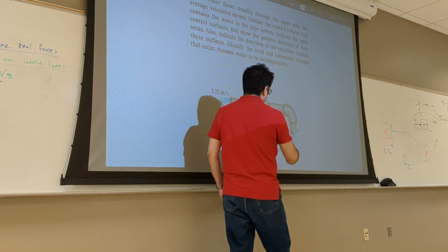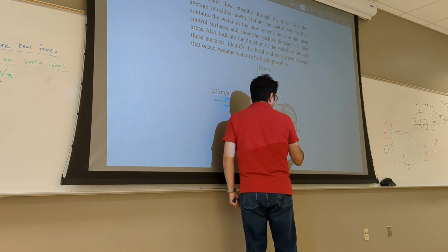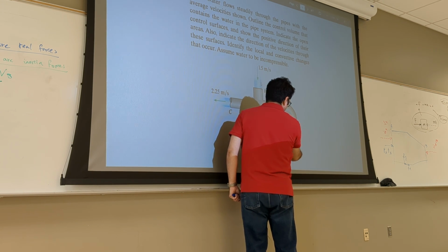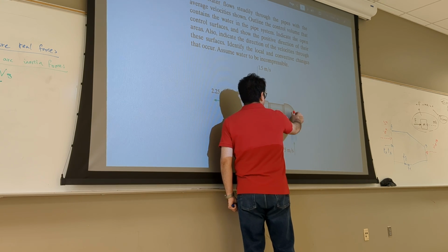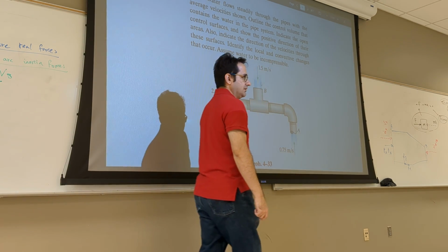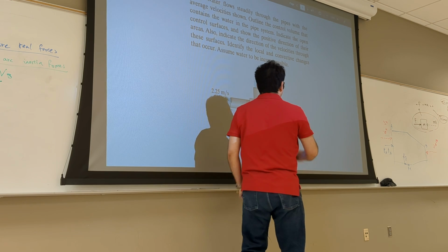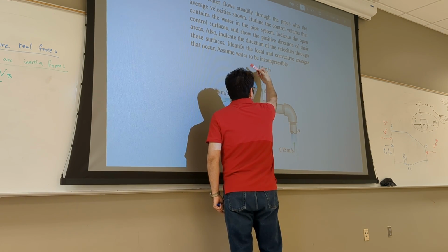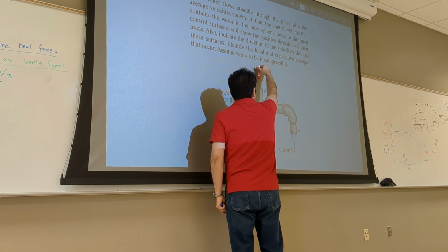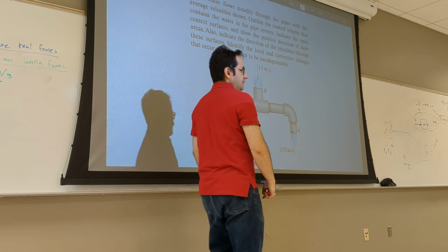Similarly here, V dot N is negative, means this way, so you just flip the sign for the real one. But when you put it in the FBD, dash, dash, dash, going up. And it's N dot A here. Same here, V dot N is negative, and the velocity is this way, so the actual one is this way. When you put it on the FBD, dash, dash, dash, goes down.